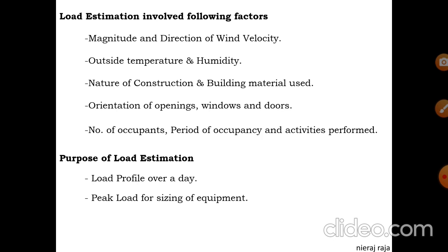In the VCR cycle, the four components you have are the compressor, condenser, expansion device, and the evaporator, or cooling coil or heating coil. To decide these, you need the peak load condition, the maximum energy which needs to be transferred. Heat may be added or it may be removed. But getting the peak load is only for getting the optimum size of the equipment.